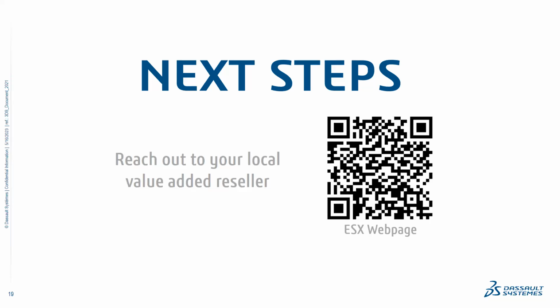Okay, sure. The timing of this question and this webinar is really good, because just a couple of weeks ago in April, we released the FD 02 release of the 3D Experience platform, and in that was a set of enhancements in this ELG tool that JP describes. It's the first release where Electrical Schematic Designer ESX can in fact connect to the ELG 3D tool for CATIA. So CATIA users, if you're involved in machine design, for example, are now able to connect to the 3D tool to add your cables, wire in sensors, power motors, and determine which paths are preferable within the machine, all those kinds of things.